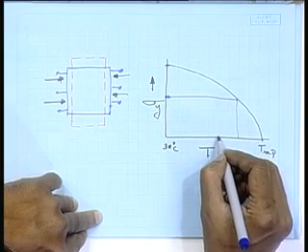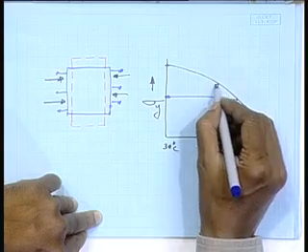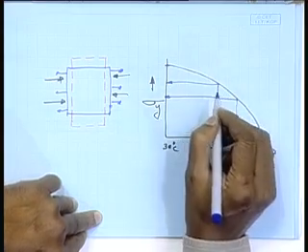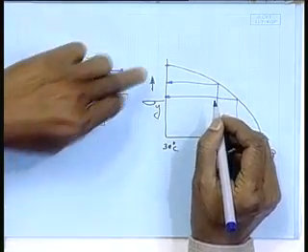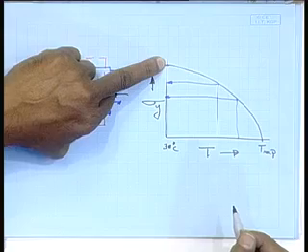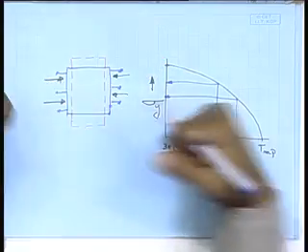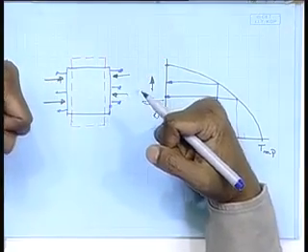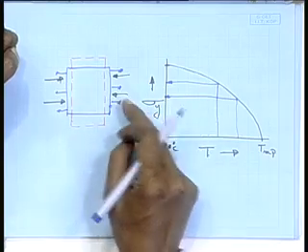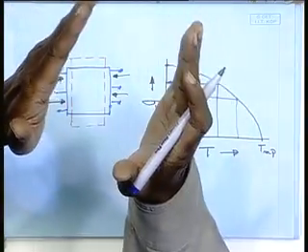Gradually, as it is cooling down, the temperature is coming down and the yield stress is gradually increasing, but it is always less than the normal yield stress. So, the compressive forces as well as the natural contraction are taking place more comfortably, I can say, because now I need a lesser load to deform it.